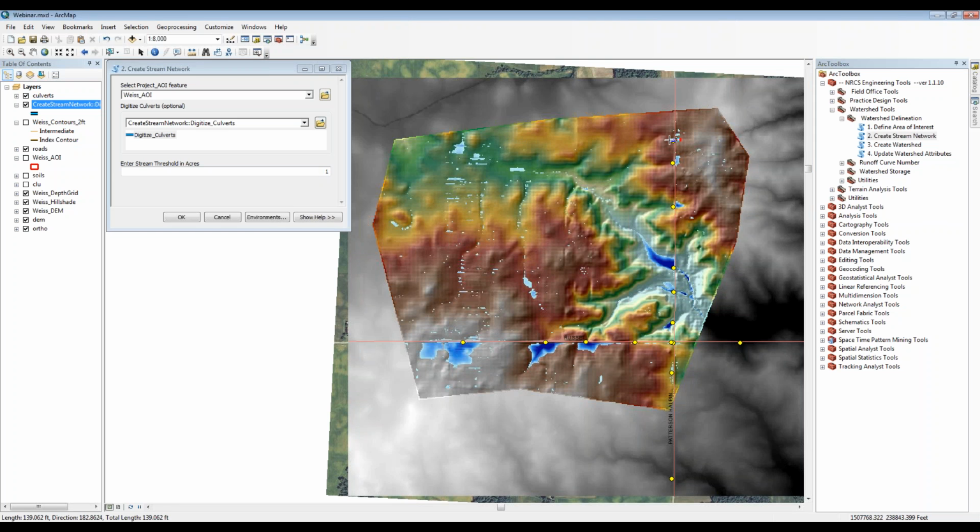Okay, here we go. Digitizing culverts. I click once to start. I click twice to end. The biggest mistake I've made is not drawing them long enough, so now I tend to draw them a little too long. I'll digitize every culvert in my watershed and those adjacent to my watershed just to make sure she's not routing flow through the side ditch into my watershed that shouldn't be in there. So right now I'm digitizing outside of my watershed. Both of these are out, but I tend to be overly cautious.